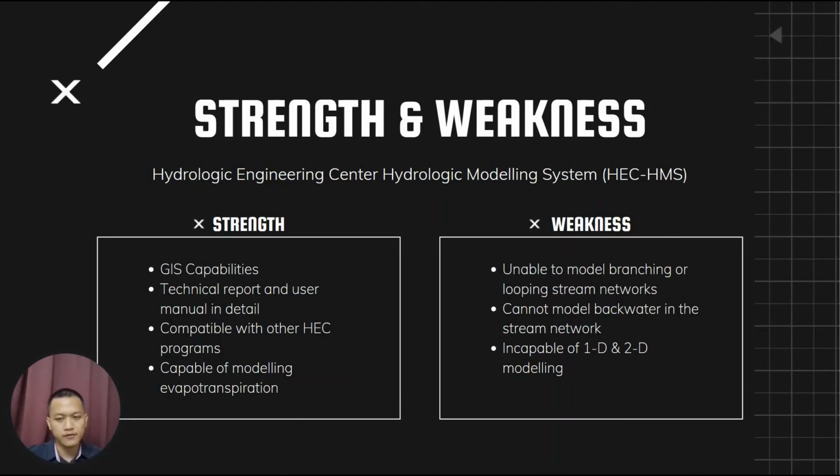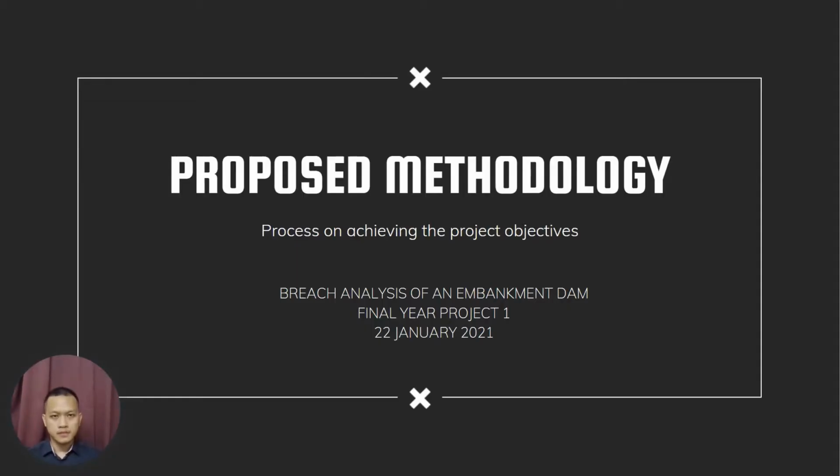Next, its strengths and weaknesses. It has a strength that it is compatible with other HEC programs, and it is also capable of modeling evapotranspiration. Its weaknesses are that it is unable to model branching or looping stream networks, and it also cannot model backwater in the stream network.